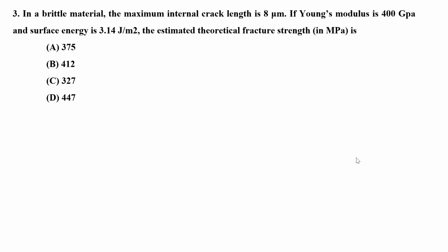So, first, what is the equation or the theory that we use in solving this kind of questions? There's a particular equation. Yeah. So, how do you identify that it's Griffith theory? Yeah. So whenever there is the word brittle material, or based on the input that is given to you, that is maximum internal crack length, Young's modulus, and surface energy. If you know the Griffith equation, you can identify from the given, or based on the fact that it is a brittle specimen. From these two factors, you can say that you can solve this question using the Griffith criterion. So now that you have told it's the Griffith criterion, can you please tell me the equation?